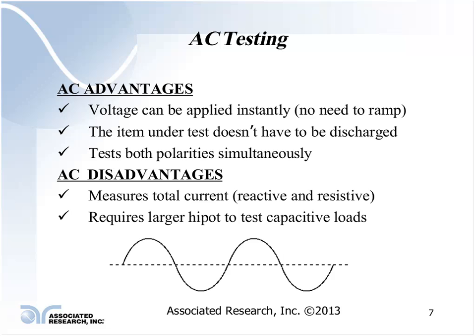Okay. In doing AC testing, you are testing both polarities during your test cycle. It is switching polarity going positive and then going negative 60 times a second, or whatever your frequency is. So it's changing polarity constantly. Why is that important? Some products, or some insulation, may be polarity sensitive. So this may be a more stringent test doing an AC test than a DC test.